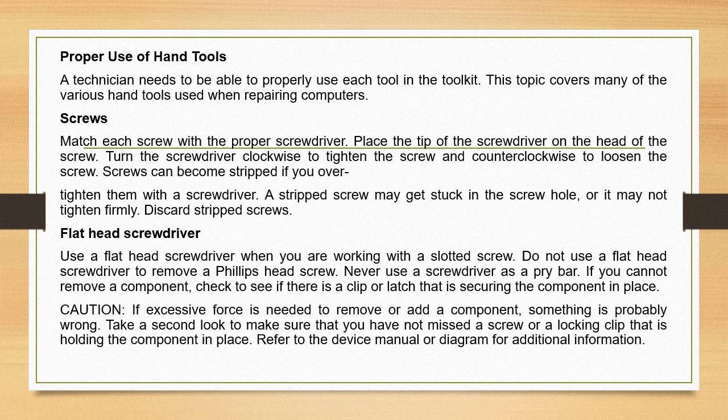If you cannot remove a component, check to see if there is a clip or latch that is securing the component in place. Caution: if excessive force is needed to remove or add a component, something is probably wrong. Take a second look to make sure that you have not missed a screw or locking clip that is holding the component in place. Refer to the device manual or diagram for additional information.